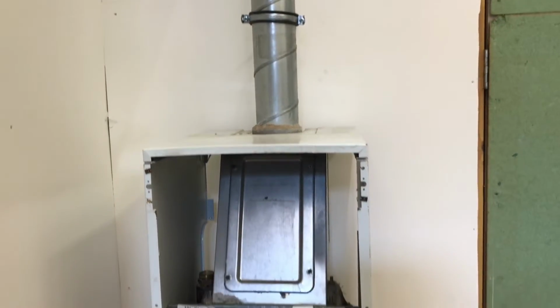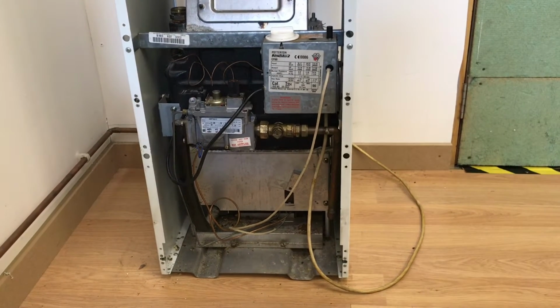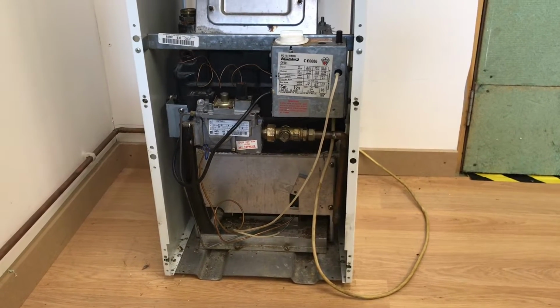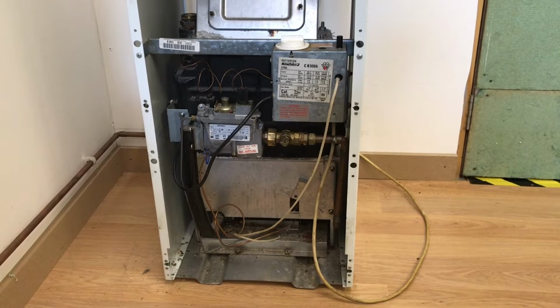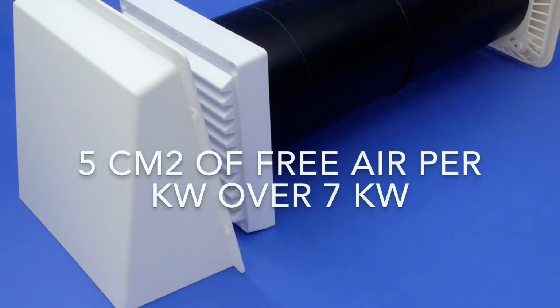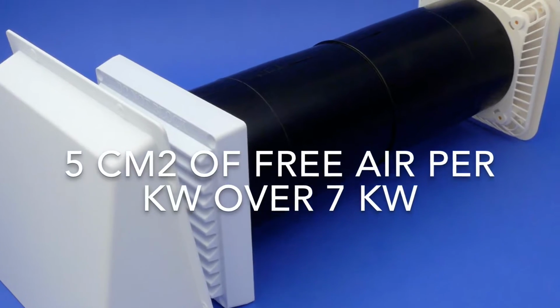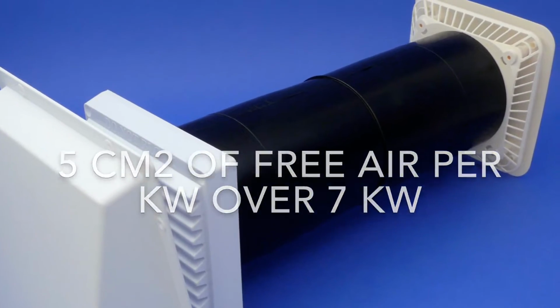Now the first boiler I want to look at is the boiler behind me, which is an open flued floor standing conventional boiler. So let's have a look at that more closely. The reason why we call it an open flued boiler is because it gets its air for combustion from within the room. So this boiler would require permanent ventilation provided through an air vent from outside to inside the room it's installed in. Open flued appliances require 5 cm squared per kilowatt over 7 kilowatt for ventilation.